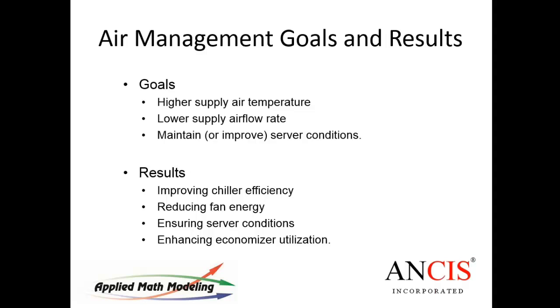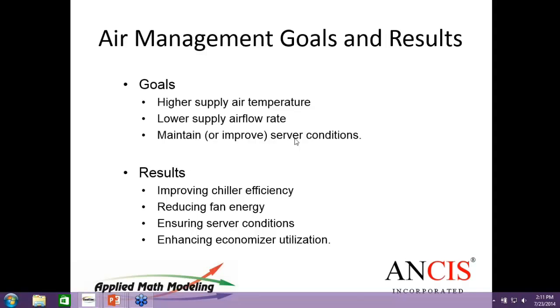And the results will be improving chiller efficiency, reducing fan energy, and ensuring server conditions. And of course, this is very important: out here in California, they're building data centers with just free cooling, with airside economizers, and if you have good air management, you're increasing the utilization of an airside economizer.